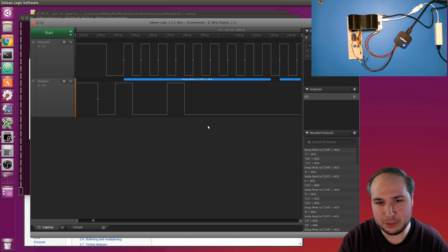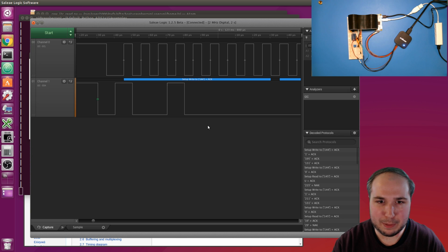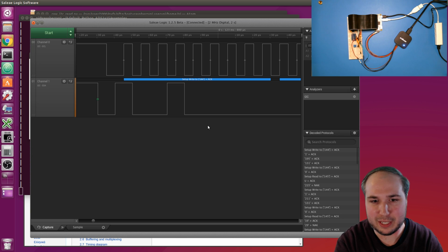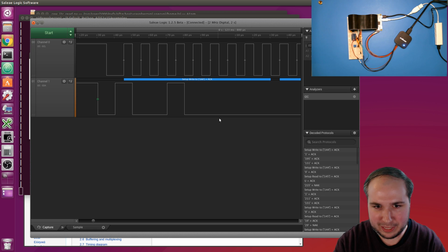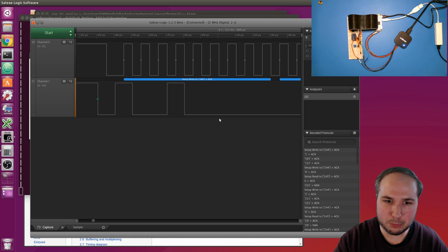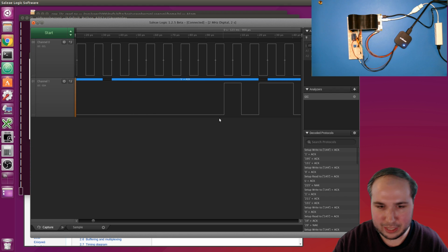And then the other cool thing about I2C is that it has this concept of addresses, so you can have multiple devices all sharing those same lines. Each device doesn't need a specific chip select line. Just with these clock and data lines, you can have up to 7 bits of devices, so like 128 devices on here. And so that's the first byte that we see: we're doing a write to this device, and now let's scooch over and see what the next value is.